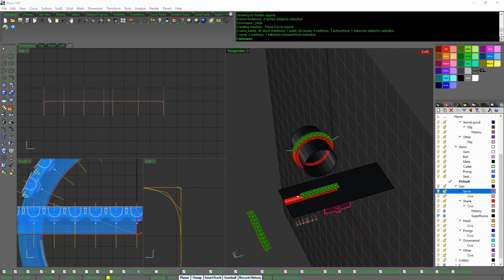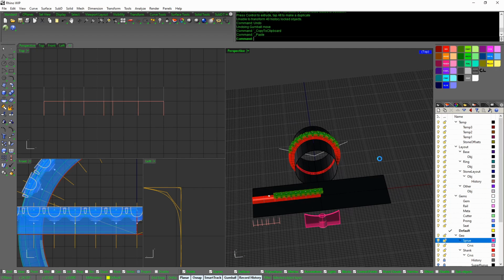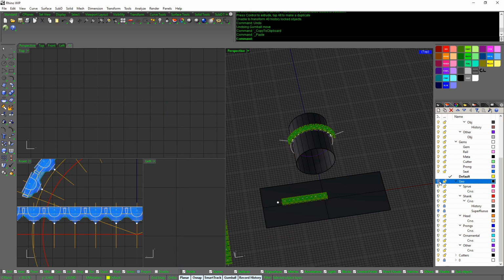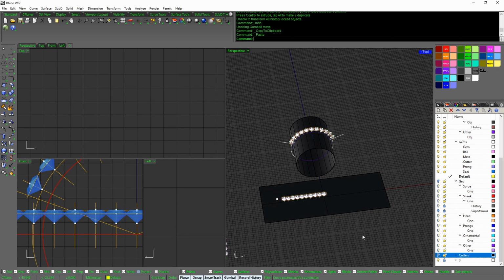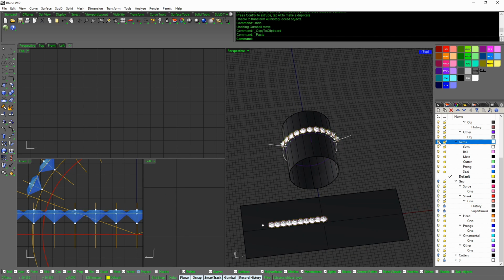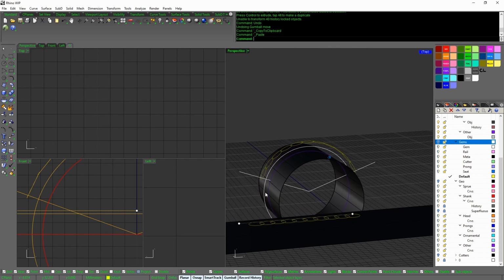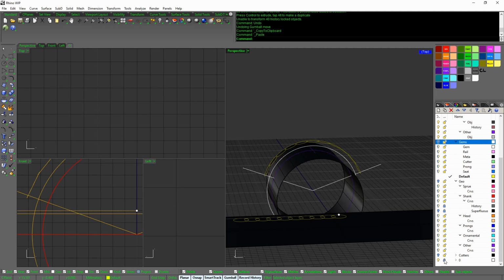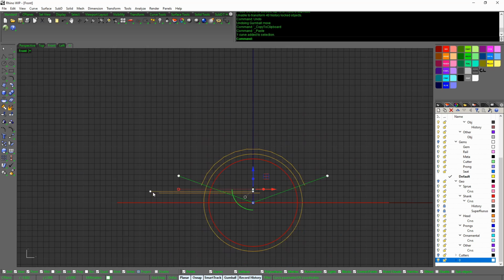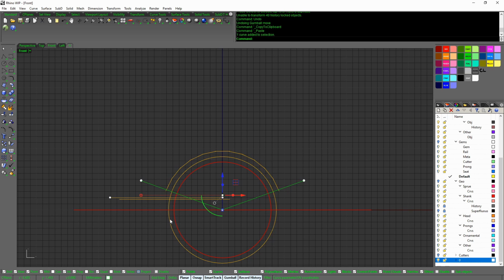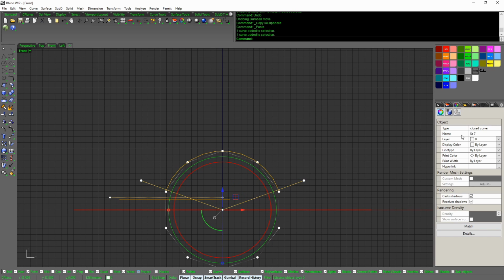So I'm going to bring in a different size finger rail, put that in, and turn off all of my geometry and cutters, and the gems, so I can see what's going on. You can see that I've got this white curve that just pasted in. My white layer is my reference, so I always keep it locked. That's my 10 o'clock. If we're looking at this like a watch face, from 10 o'clock to 2 o'clock, that's where I want my stones to flow. Also, that is my finger rail, size 7.